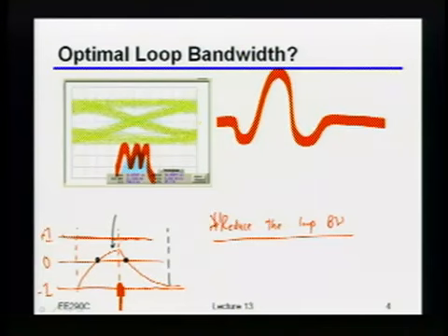Now, there are indeed things that will cause low frequency drifts, like shifting the entire sequence around. Those you still want to be able to track. But certainly anything that's even close to a cycle, or maybe 10 cycles, or even about 100 cycles or so, your best bet is to not even try to catch it, to just ignore it and stay where you used to be. So if that's the case, that really does say what you'd like to do is reduce the loop bandwidth as much as you can. Okay?